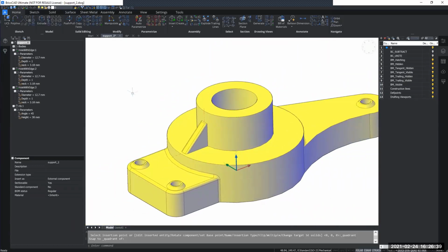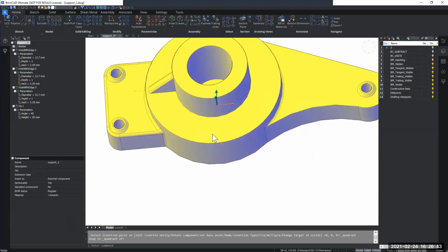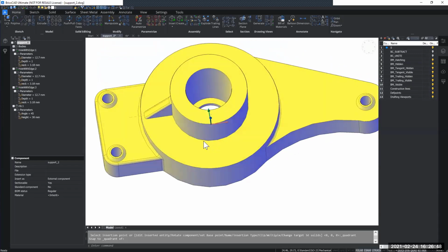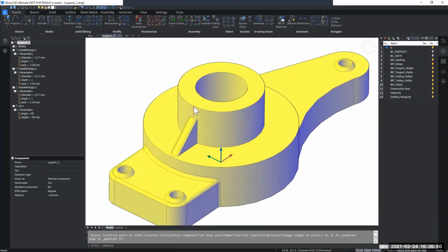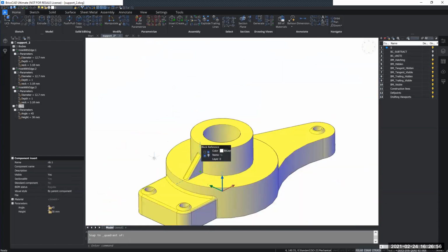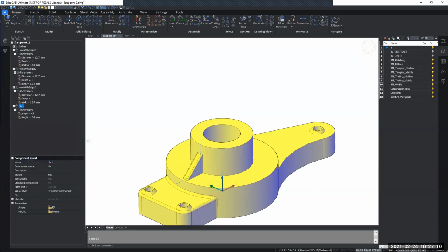Now, following this, I want to have more than just one support here. I want them to move around my circular geometry here. So I can then select my part. I can select this line as this is a part of the block reference. I can also go to the mechanical browser, locate the rib, right-click it, and then I can choose the select sub option.